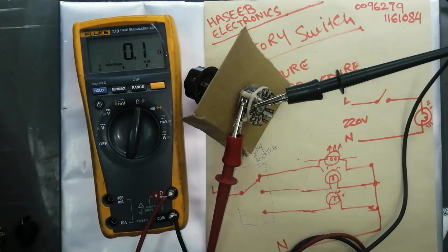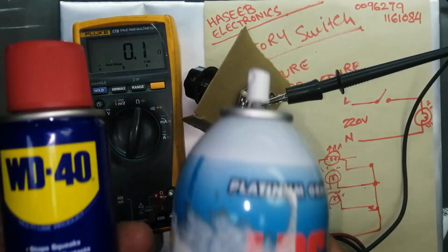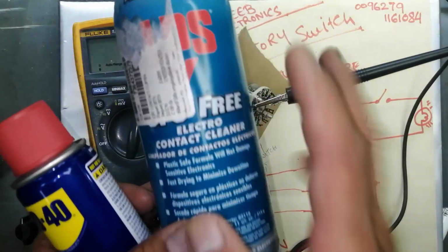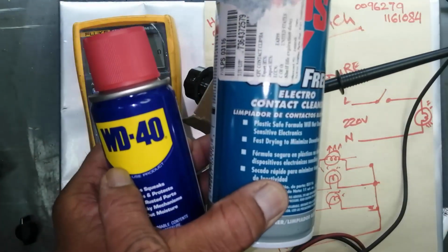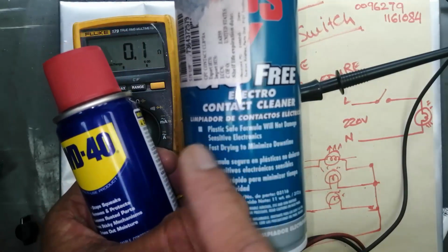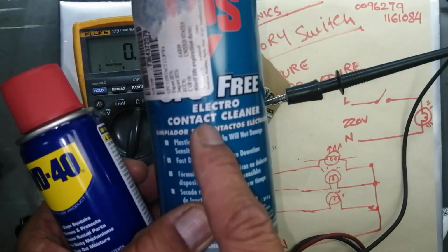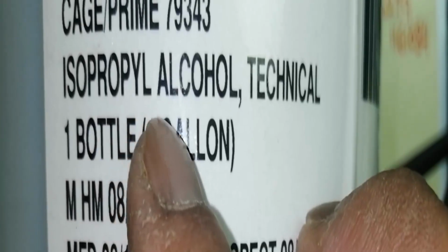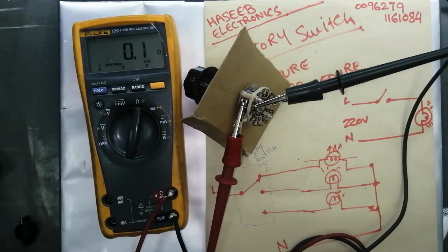How to overcome this issue? You have to use contact cleaner, not WD-40. This is oily. This one is oily. This is oil free, or you can use technical isopropyl alcohol, or you can use a separate cleaner. The best